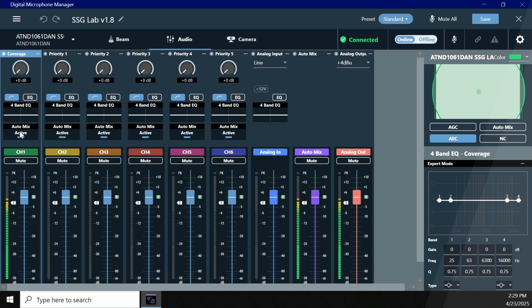And so all of that audio that you have right there, you can control. Now, typically this is kind of your split point, if you will. So you can, if you wish, take that audio from all 6 of those beams and send them out to the DSP of your choice. We've got plugins and modules for everybody from Q-SYS to Symetrix and a ton of others in between. And quite frankly, it's Dante, so you can take that Dante output to anything if that's what you wish to do. But like I wanted to talk about today, the DSP that's in here is actually very powerful.